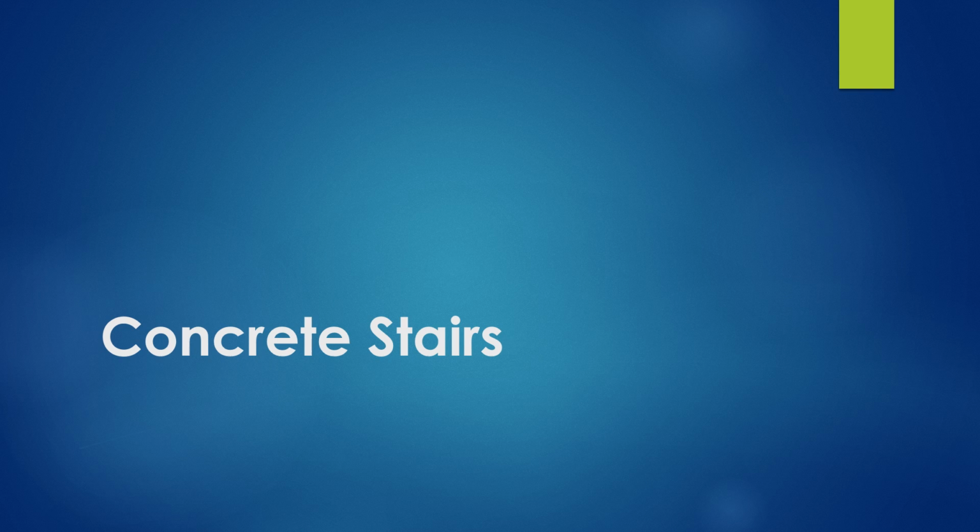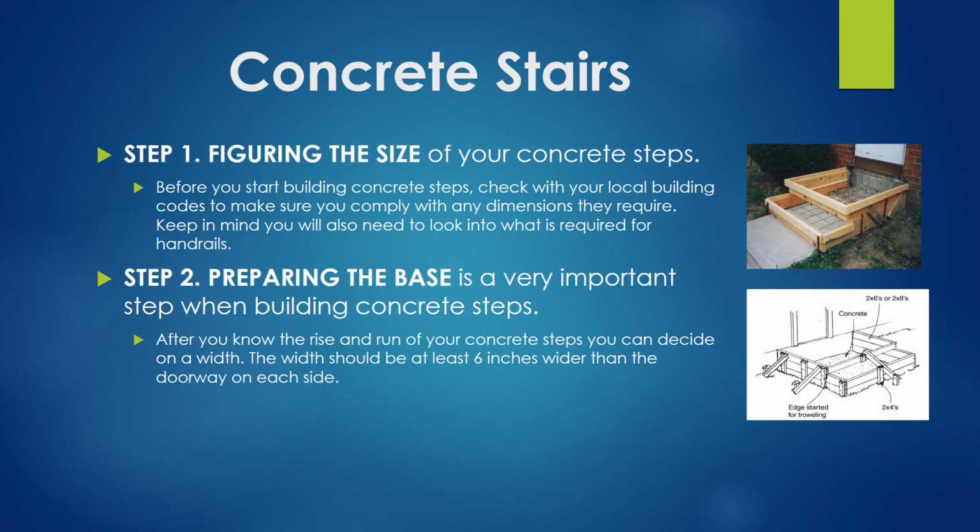We will now go into some specialty areas, one of which is concrete stairs. First part of concrete stairs is to figure out the size of your concrete steps. Before you start building concrete steps, check with your local building codes to make sure you comply with any dimensions they require, and also keep in mind that you'll need to look into what is required for handrails.